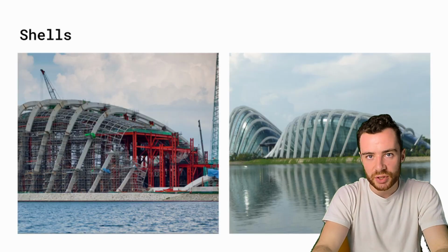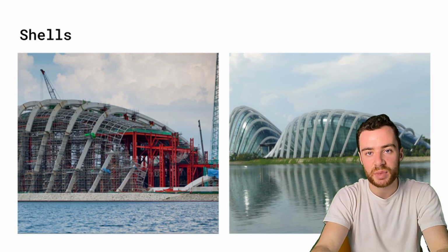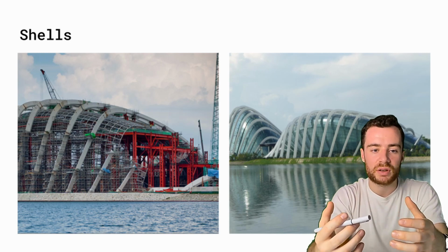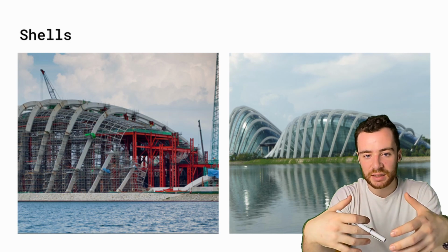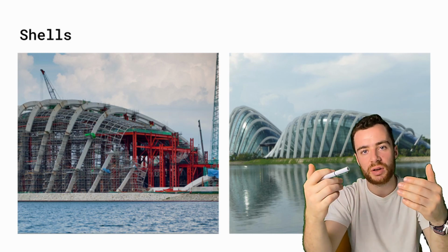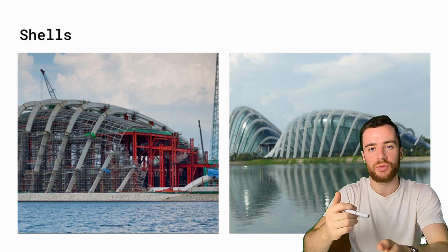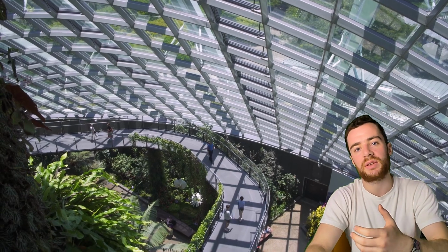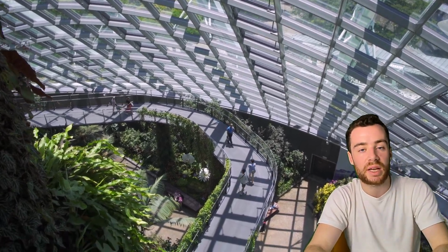A modern reinterpretation, for instance with the conservatories by Wilkinson in Singapore, where essentially it's a composite structure formed of a grid shell that works in tandem with an external superstructure of radially arranged arched steel ribs. Now, they were introduced primarily to address the lateral loads to the grid shell, but they also give the conservatories, of course, a distinctive organic look.